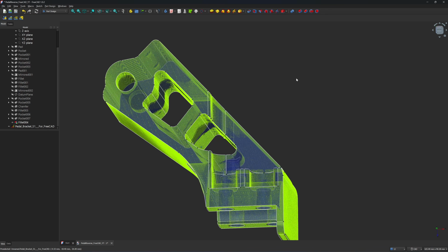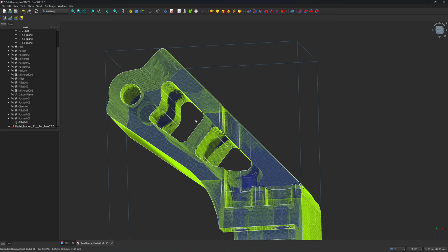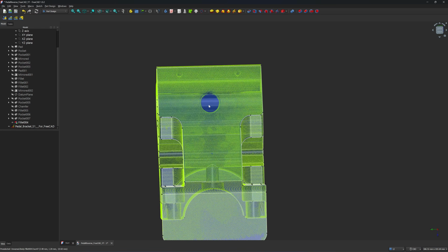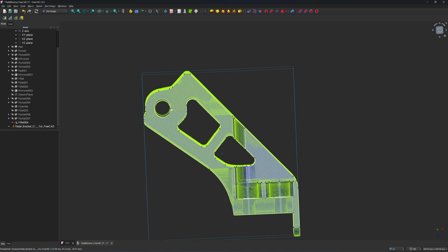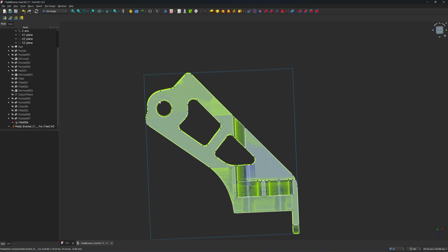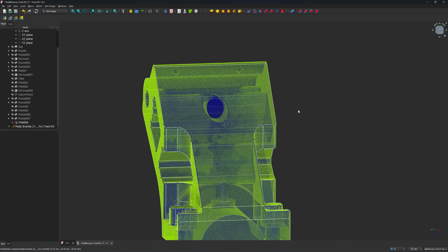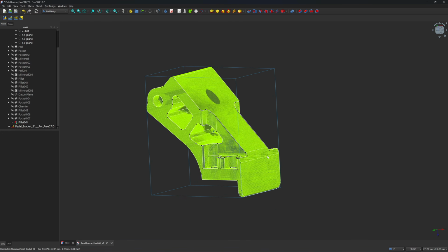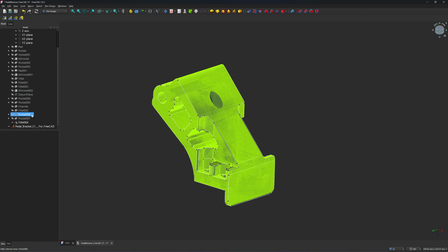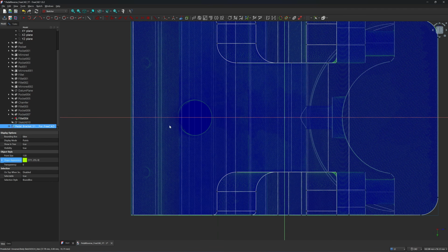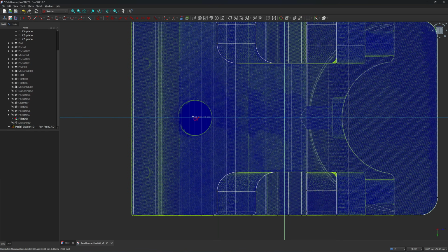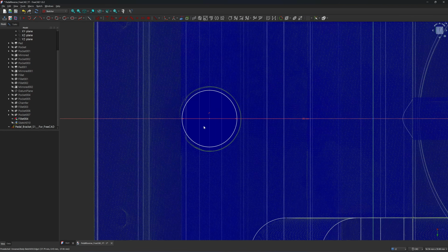Okay, one more hole. It's an M8 screw thread. For the grub screw, the grub screw will be inserted through this hole, and it will be used to create friction for the pin. So I'm going to create a plane here and cut the hole through this. Okay, the steps are simple. Turn off the point cloud, click on this plane, click on the sketch. I'm going to draw the hole. It's M8, so I'm going to draw an 8 millimeter diameter hole and put it here.